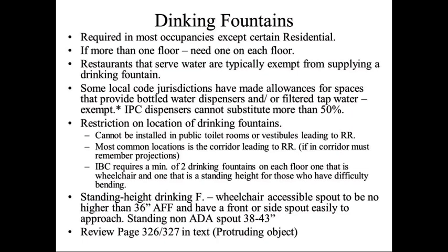You also have to look at the restrictions on location of drinking fountains. They cannot be installed in public toilet rooms or vestibules leading to restrooms. The most common location is in the corridor leading to the restroom. Remember your projections. You can't project into that hallway or corridor.